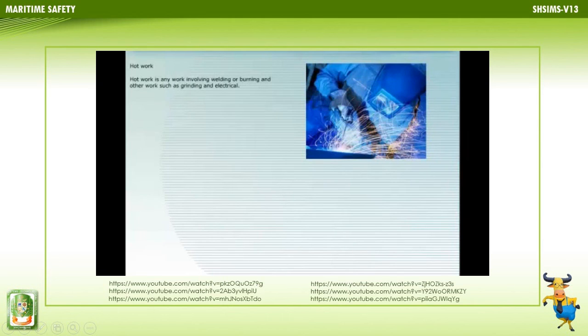Hot work is any work involving welding or burning, and other work such as grinding and electrical work. Hot work outside the engine room workshop should be prohibited until safety considerations have been met and hot work permits have been issued.